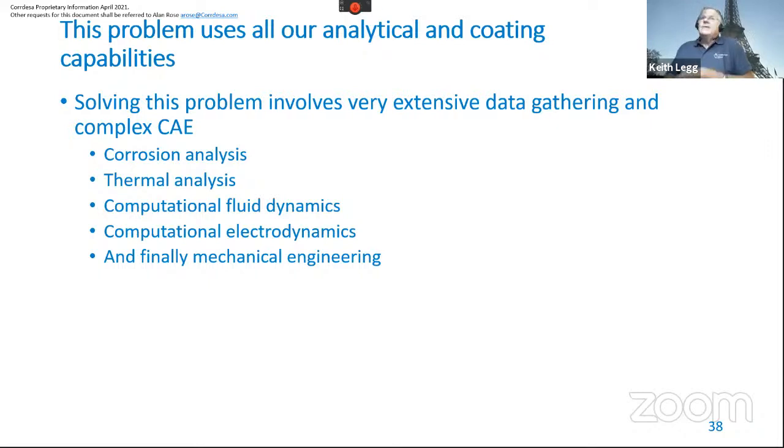At that point, what you've now got is a single phase gamma phase zinc nickel alloy, and that gives you the highest hardness, the best corrosion resistance, and you're not going to have different areas with different zinc nickel contents. So that's the best coating. In brush plating, you have to have less nickel because you have less control over all that, and so brush plating coatings are 13% nickel.